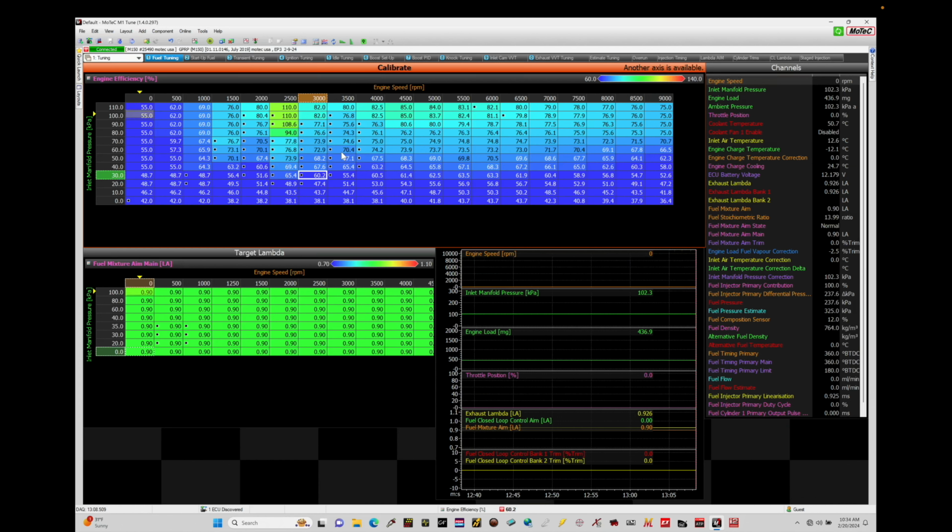So we're going to walk through and demonstrate the process from start to finish here on our in-house test vehicle. Now, there are a few things that we need to understand before we head into dialing in our fuel film tuning. We need to make sure, first and foremost, that our volumetric efficiency table here has been dialed in 100%, meaning that at a given RPM and load threshold in our table we are hitting the desired target lambda coming from our target lambda table.